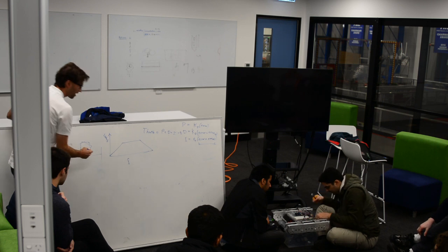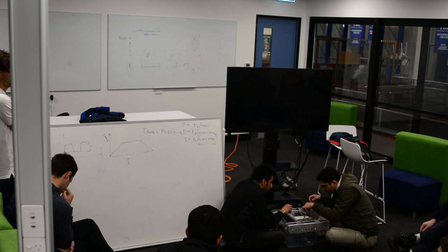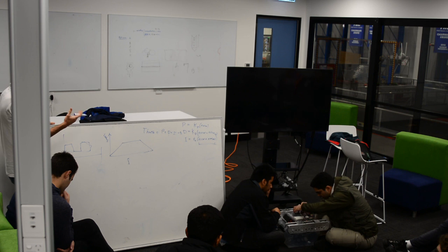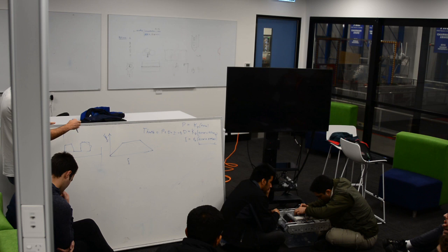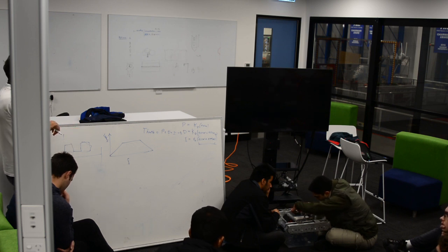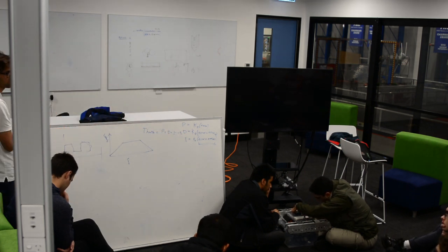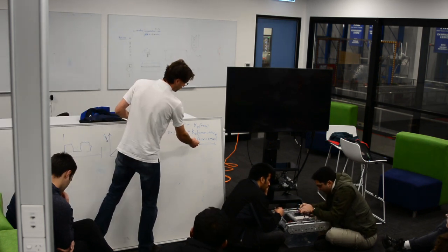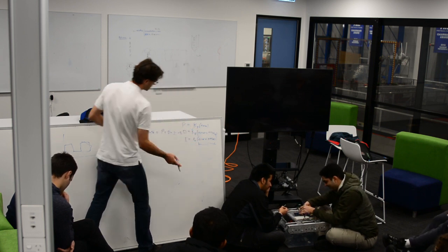One way that I have done that, I haven't had a lot of success with it, but it does work, and it's one way the CNC speed is done: you use a metro, and every 100 milliseconds you ask how many pulses went past. You know that should be happening every 100 milliseconds. If 10 pulses went by, you know your speed is X. Then you use that in your error signal and say, am I going too fast? Okay, well, I'll increase the gain or decrease the gain. For speed control, I like an integral, because once you have zero error, it doesn't actually drift.